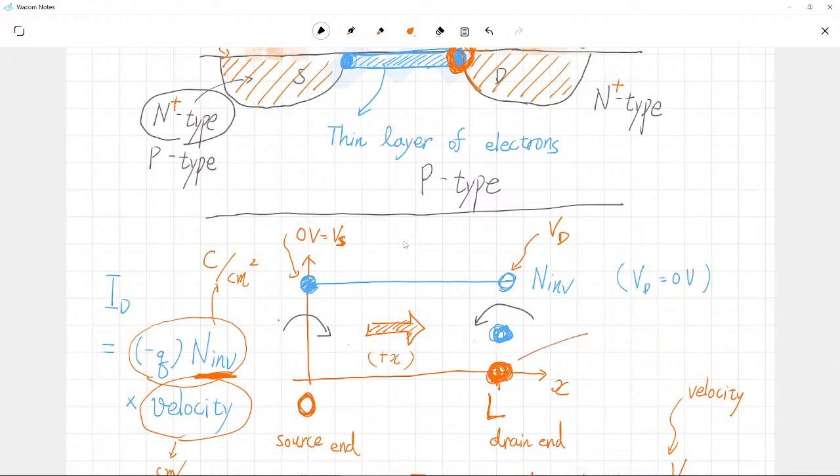So can you understand? Let's say our drain bias voltage happens to be quite close to Vg minus Vth. Then our drain voltage just turns on our MOS vertical structure, so the number of electrons will be quite small compared with the highly turned-on one at the source end.